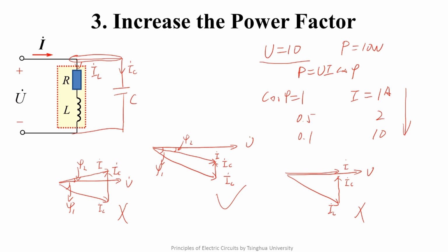With the increase of compensation capacitive current, the number of capacitors needs to be increased, so the cost of the compensation increases. In addition, if the current seen from the port compensated is capacitive, then the circuit might be resonant and produce bad effects. We will discuss the resonance in lecture 72.